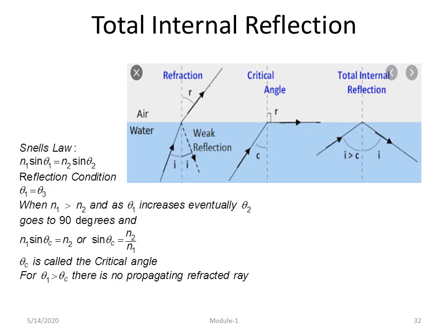What is the light collecting capacity? What should be the angle of incidence to the optical fiber? The angle of incidence phi 1 should be greater than the critical angle, and at that angle, the light transmitted within the core will get total internal reflection, so that it is completely confined within the optical fiber core. That is required, and for that angle of incidence, what is the numerical aperture of the optical fiber? So numerical aperture is the light gathering or light collecting capacity. Derive the expression for numerical aperture using the ray theory model.